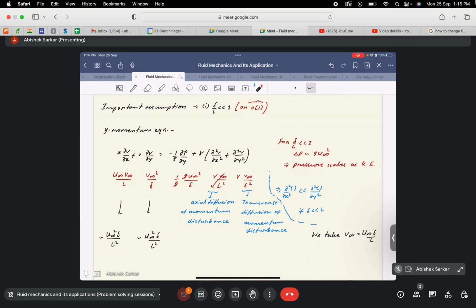See, again, that's very interesting. Since boundary layer flows are usually inertia driven flows, because the boundary layer is driven by the inertia of the incoming flow, now the pressure scales as rho u infinity square. There's so much concept to observe, right? In the previous case we saw that our pressure was scaling as mu v naught by d. But now our pressure scales as rho u infinity square. Now if you substitute delta P as mu v naught by d, this analysis again becomes invalid, or there will be certain complications. So it's very important to know which scales govern the flow field as well as the driving forces that drive the flow.